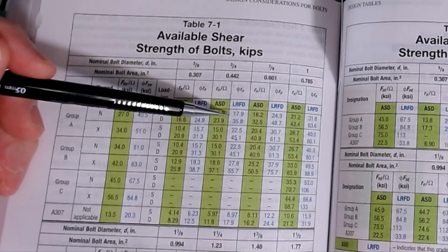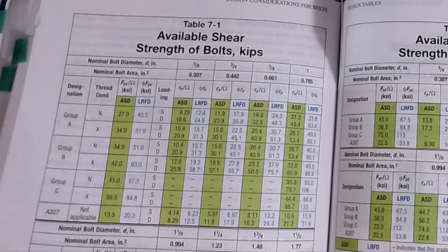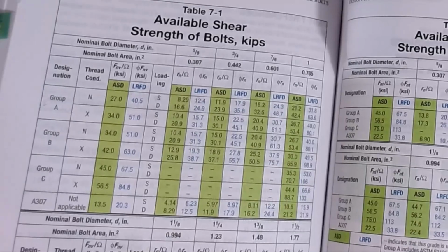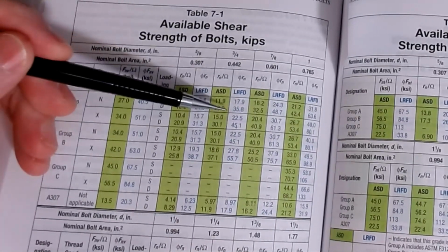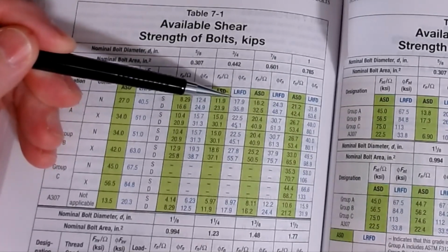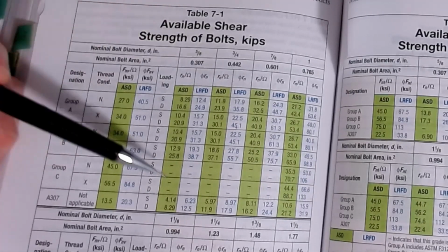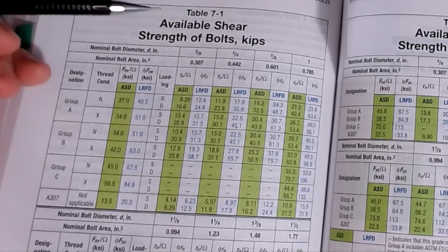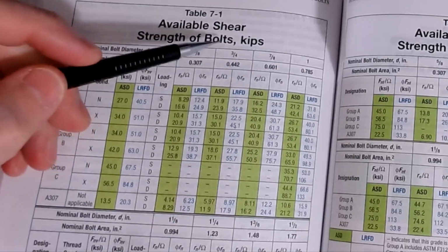And so I can use that to then get a guess on the number or the quantity of bolts that I need to have in my system, and with that, then we can start playing some games relative to how I am going to lay this out. So I'll use this number often as a first guess to get a sense of, do I need 4 bolts or do I need 16? Big difference, and how I lay this out can dictate things like where the bolts are located, do I bolt the web of an I-beam, do I bolt only the flanges, all those kind of things start to factor in to our selection. So we'll take 3/4 as a first guess.